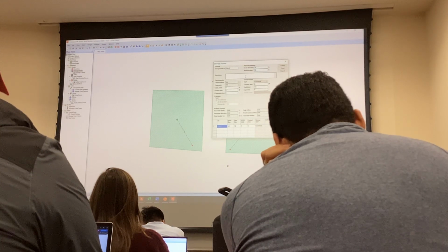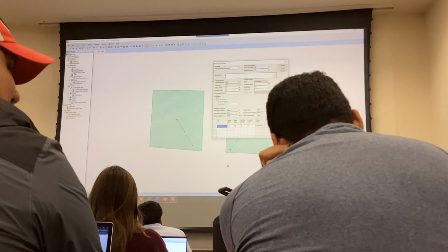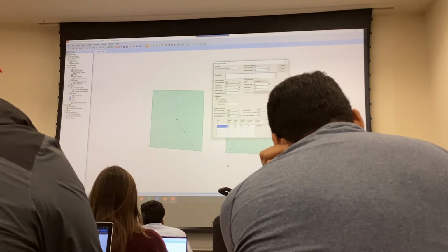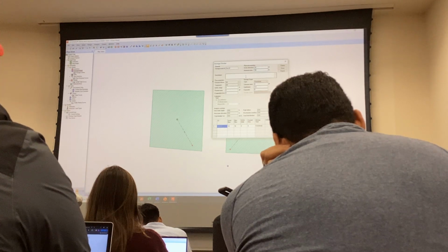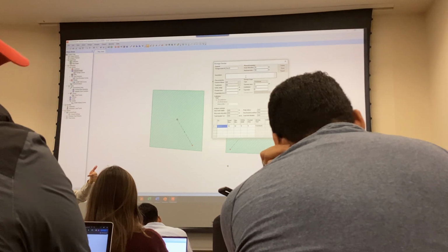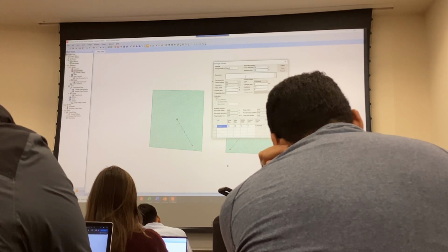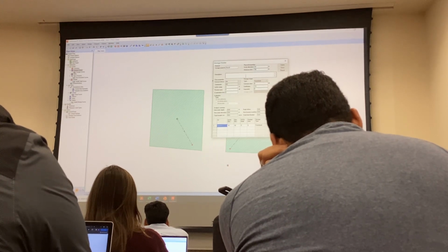Once you specify the elevation, okay, what you physically did is that you told the program that your detention basin is at a certain elevation. So now you have to check your downstream and upstream. Okay. The fact that you are putting something into your detention basin needs to come from a higher elevation. The fact that you're releasing from a detention basin to somewhere else needs to have a lower elevation. So now your program knows what this base elevation is for your detention basin. So when you put in the other information, containing what goes in and what comes out, okay, that's going to be important. And that's part of the routing mechanism.